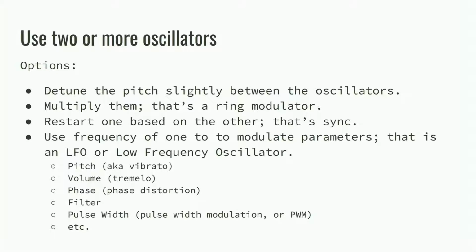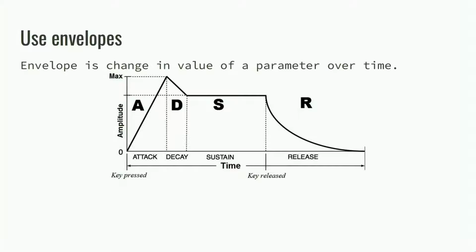Right, so that's what is actually used on the Roland Juno 106 and HS60. So you can use envelopes, right? This is a standard envelope, the attack, decay, sustain, release envelope. Sustain is when you're holding the key down. And the rest of them, you have this little peak there, the little pop in the beginning, which might not be a pop. It might just be a smooth thing if it's strings. And then the release, which could be instant if it's an organ, or it could go very long if you have a bell sound.